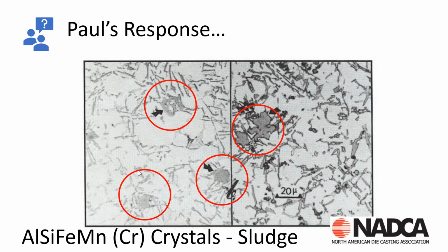If we were to look at photomicrographs of our castings, we can see those sludge points in our material. If we're machining these castings and we hit any of these, they are going to be more dense. Now, this isn't necessarily corundum level of density, but the increased specific gravity, the increased density could chip tools, can break tools, can smear the casting. So if you're machining across these crystals, just like any other imperfections in our metal, we could affect the machining operations.